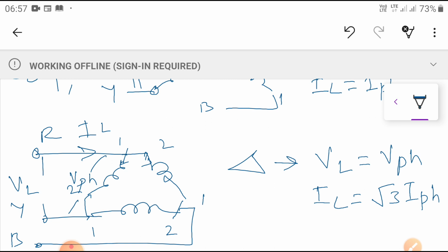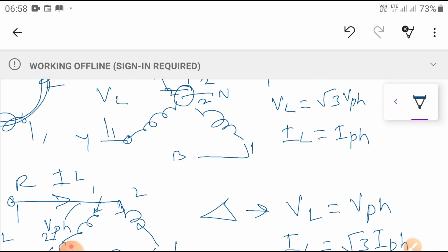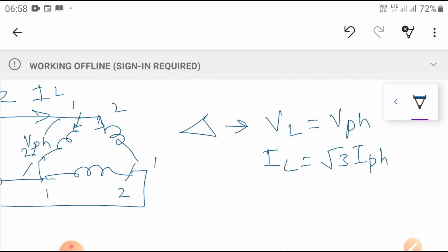Dear students, all these things you have already learned at secondary level in three-phase circuits. The same theory can be used in our applications, in place of three-phase induction motors. You have already done many problems on star to delta and delta to star conversions and three-phase circuits. The same concept we are going to use in our induction motors to reduce the starting voltage, and correspondingly it reduces the current.